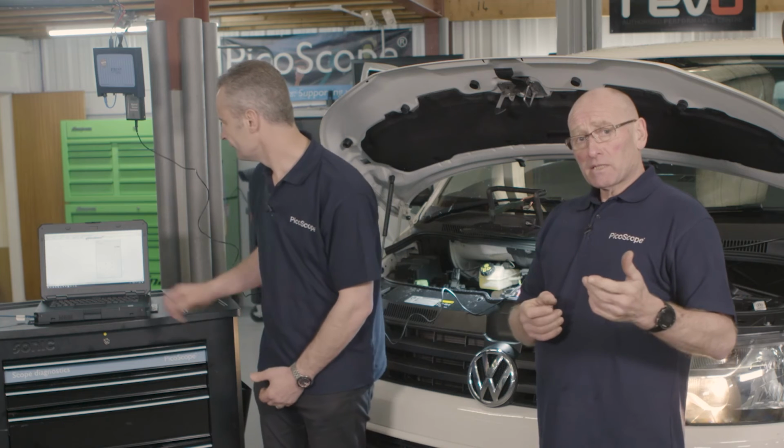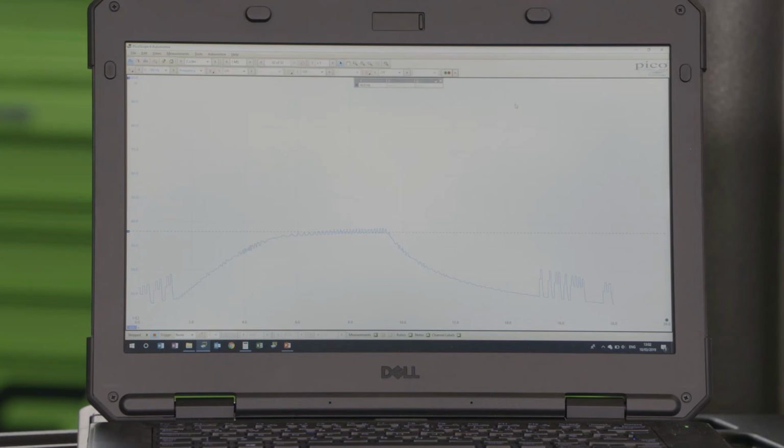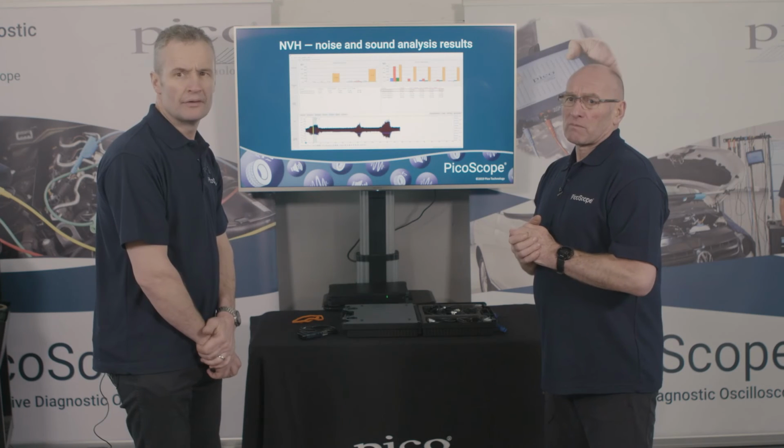Sure. It may be worth mentioning also that your channel input command has been set not to AC or DC, but to frequency to obtain this information. Yeah, the frequency coupling of PicoScope, so that's available in the current 4000 and previous 4000 generation of PicoScope.